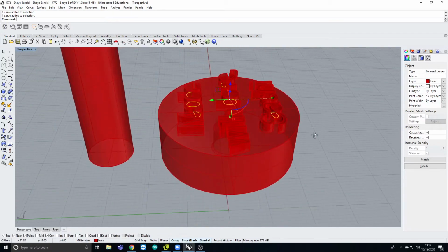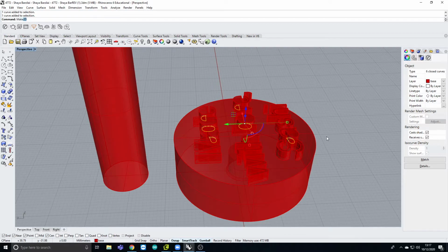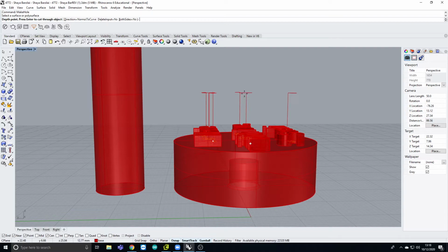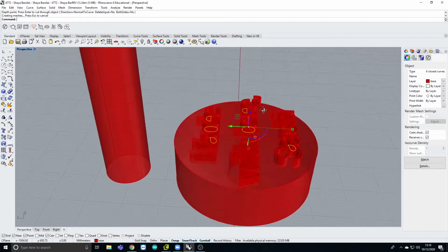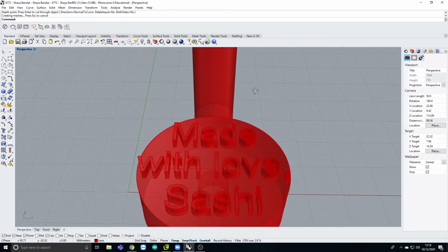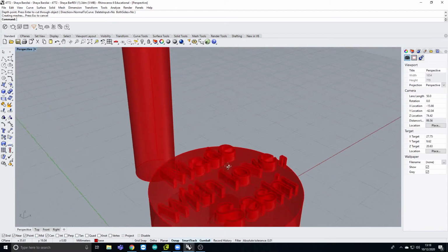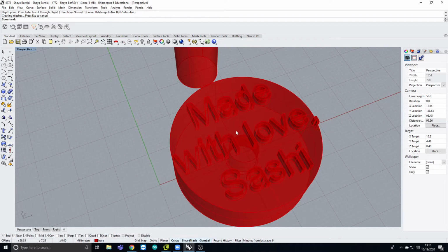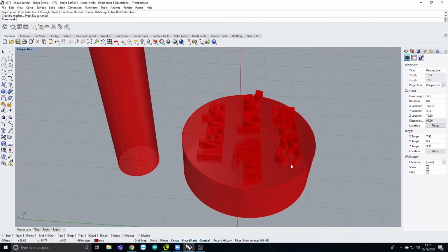And now I'm going to use the command called make hole. Make hole. What hole do I want to make the cut in? Well, it's this big poly surface, and I've already joined it, so it makes it easy for me to cut it because it's considered a single surface. And I'm just going to pull them all the way out and click down on it. And now I have nice holes in there that actually form what the words are supposed to show.